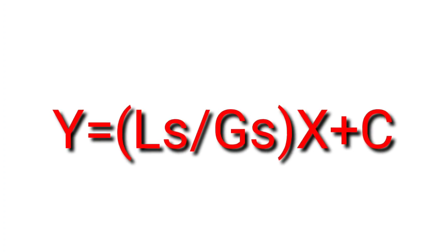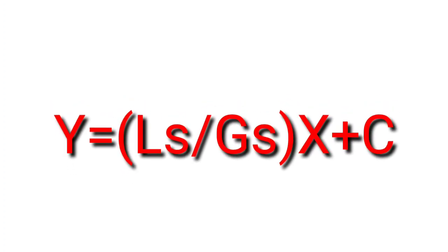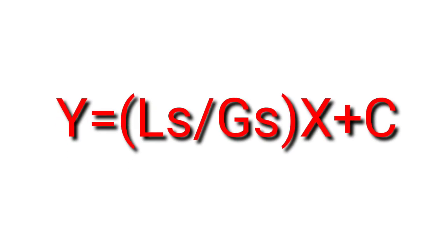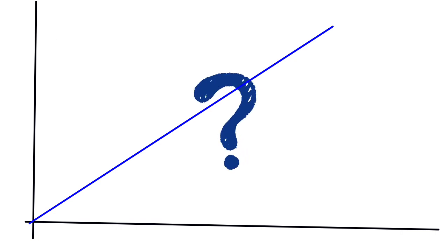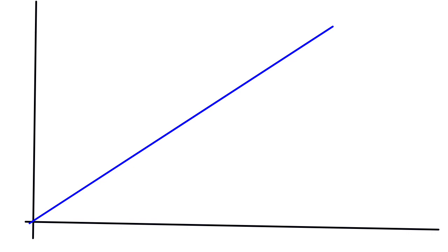Now the question is, if the operating line is same and equilibrium line will also be same, then how the y-x graph will look like? Will it be same like absorption, or where the operating line will lie? Will it lie above the equilibrium line, or will it lie below the equilibrium line? So that's the question you have to answer. In this stripping kind of situation, the operating line will lie below the equilibrium line. So that was our first important concept.